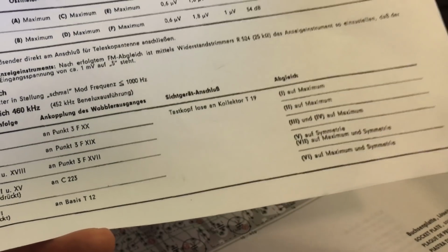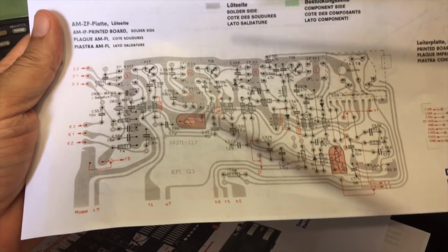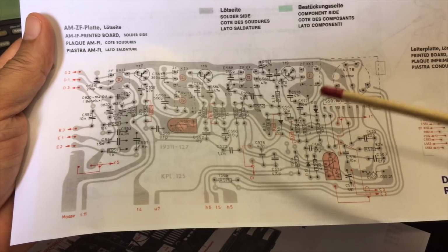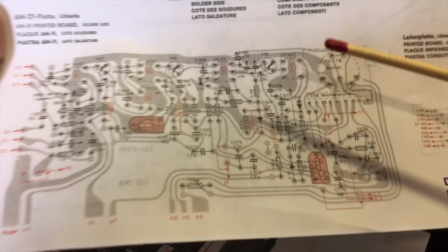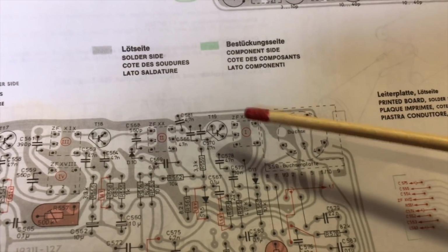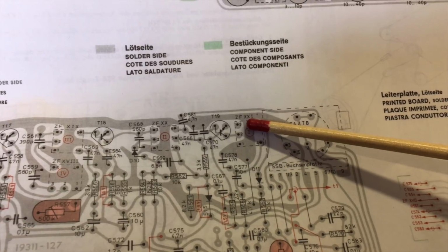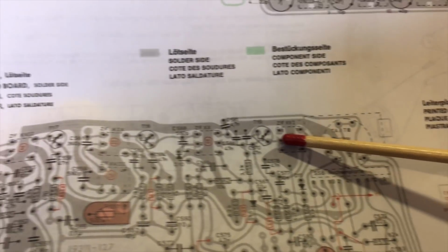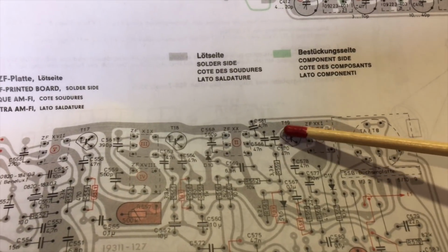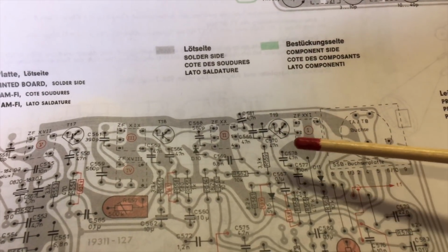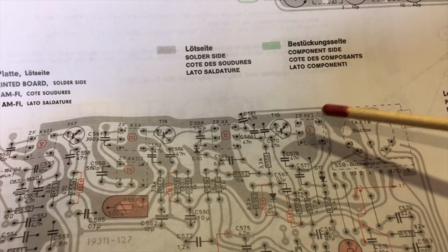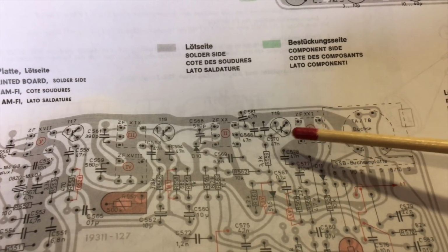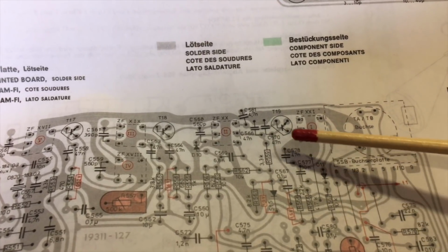Now these are quite clear on the other drawing, on the schematic. On the actual image of the board, it's not easy, but you can see that it says there, filter 21, ZF21, and that's adjustment point 1. There's T19, the transistor they tell us about, and we've got to find the collector of that and connect to the collector of that.